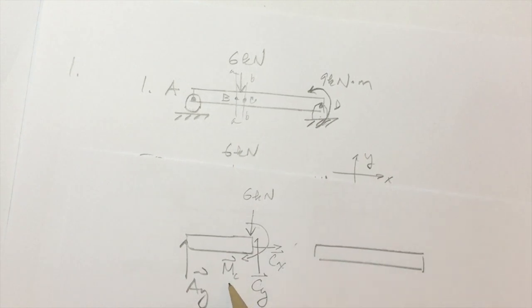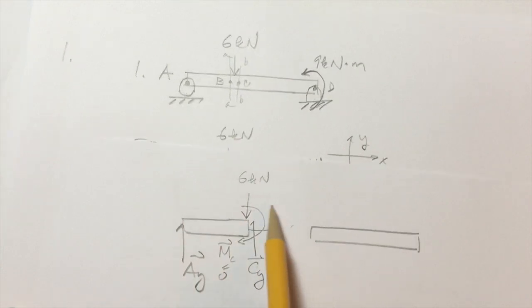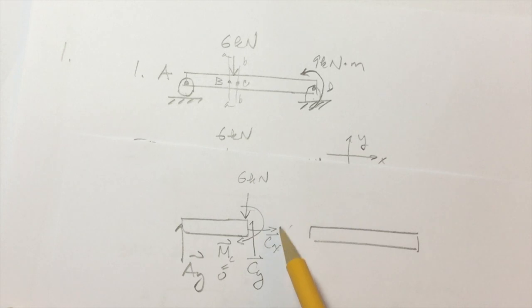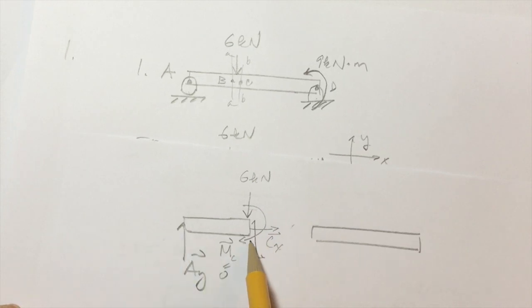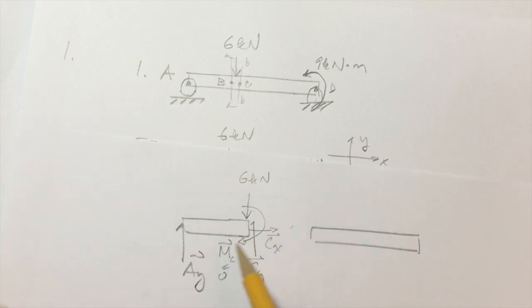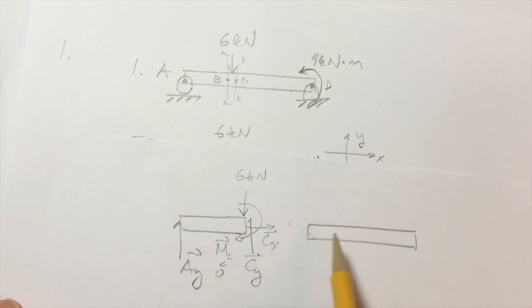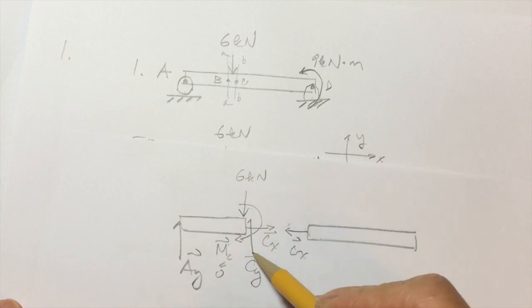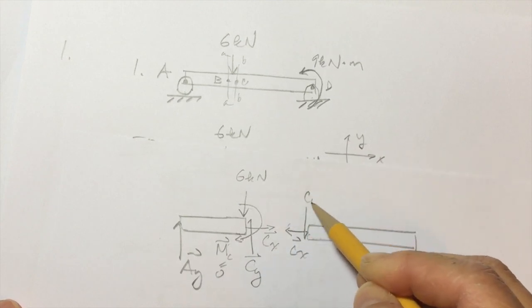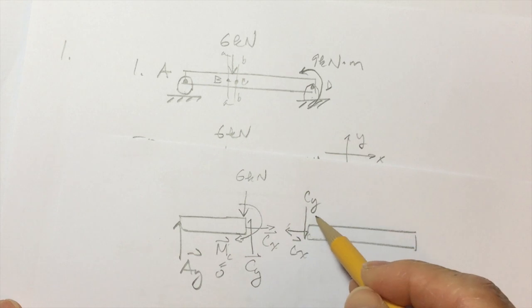And I know that's equal to 0 because if I were to do a free body diagram analysis of this segment, there's only one moment vector on this diagram, therefore the sum of the moments must equal 0. And the reaction moment on this member would be equal and opposite to this, and equal and opposite to that moment.